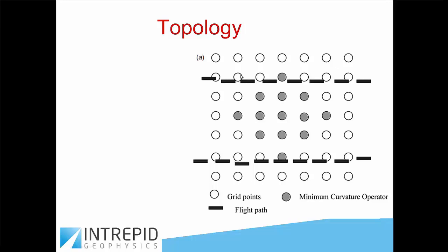And if you imagine your flight lines or observation points to be along those lines that are dashed, you can see that your operator, if there is no more than 5 cells between one line and the other, can span between the observations. And that's about as far as you can go with a traditional minimum curvature operator without getting so that the grid remains supported by real observations.